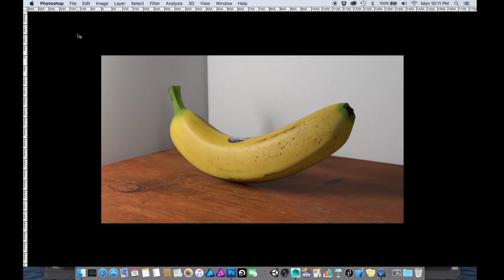So what we're going to do is create three texture maps. We're going to do a diffuse map, which is the basic color of the object. That's going to be a base. Once we have a diffuse map, we can usually, with a little bit of work, extract out some of the other maps we can use to generate some surface material properties. So the three we're going to do is a diffuse. From the diffuse, we're going to extract out a reflection map.